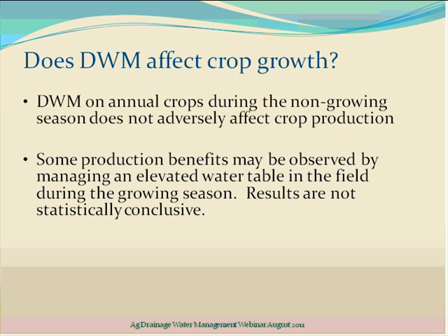Does the DWM affect crop growth? Now, that's a question that's often asked by producers. So they want to know, does it help crop growth or hurt crop growth to install the practice? And during the non-growing season, DWM does not adversely affect crop production. During the growing season, some benefits may be observed by managing the elevated water table in the field. So it's not conclusive, not statistically conclusive anyway, but we do see some minor increases in production.